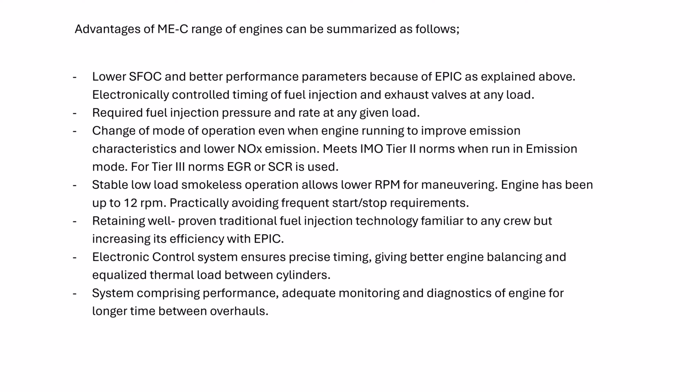Economy mode and emission mode are two modes of operation of an engine. In both modes, it meets Tier 2 norms, but it doesn't meet Tier 3 norms. In emission mode, NOx emission is lowered further than the Tier 2 norm, but does not meet Tier 3 norm. For Tier 3 norm, SCR has to be used. HPSCR, LPSCR, as I explained before: SCR put before the turbocharger, SCR put after the turbocharger, or exhaust gas recirculation.